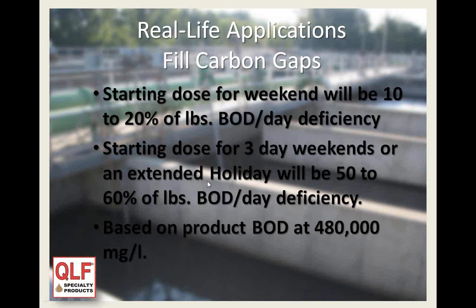Okay, filling the carbon gaps. When you look at filling a carbon gap, that's like when the industry shuts down over the weekend. What we look at for dosing is about 10 to 20% of the pounds BOD per day deficiency. So let's say during the week you're getting 1,000 pounds or 2,000 pounds of BOD a day. On the weekend you're getting 1,000. We would look at feeding somewhere between 100 to 200 pounds of BOD a day of our product.